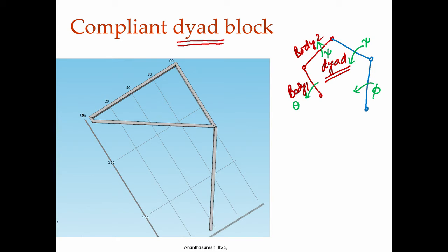That is, we design these dyads first, we do not design a 4 bar linkage, we will see how 4 bar linkage comes momentarily. We design dyads in kinematic literature where we take 2 bodies, one of them is specified to have some theta rotation, theta 1, theta 2, theta 3 and so forth, and other one will have psi 1, psi 2, psi 3 from first position to second, first to third and first to fourth and so forth. We have these angles of rotation.